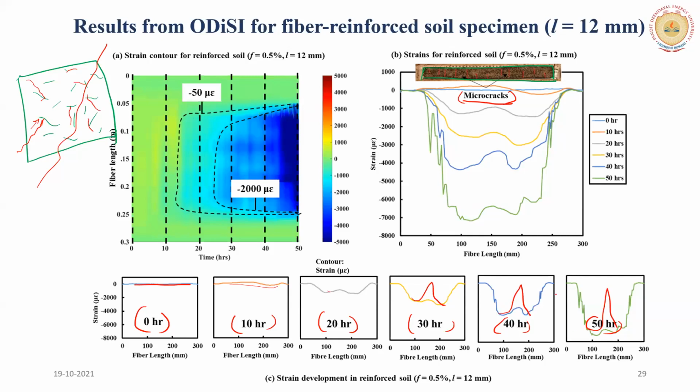It means there are small dips. There are small releases of strain because of these micro cracks, which are caught by the optical fiber. So this actually helps us understand the physics behind the reinforcing fibers: that they help in mobilizing the strains at very small strains, right? And the whole sample is held intact. There is no abrupt failure. And that is how we compared these two things with the help of the optical fibers.